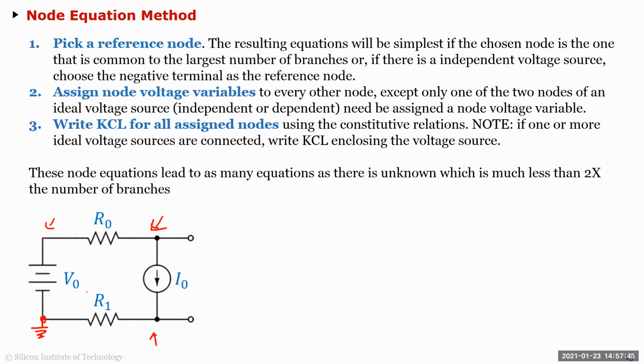The first question you should ask is, with reference to which node? If I have specifically drawn this ground, then obviously I'm saying with reference to this node. But if I've just drawn this circuit and I'm asking you what's the voltage at this point, then you should ask me with reference to what node. So in the node equation, there are 4 nodes here.